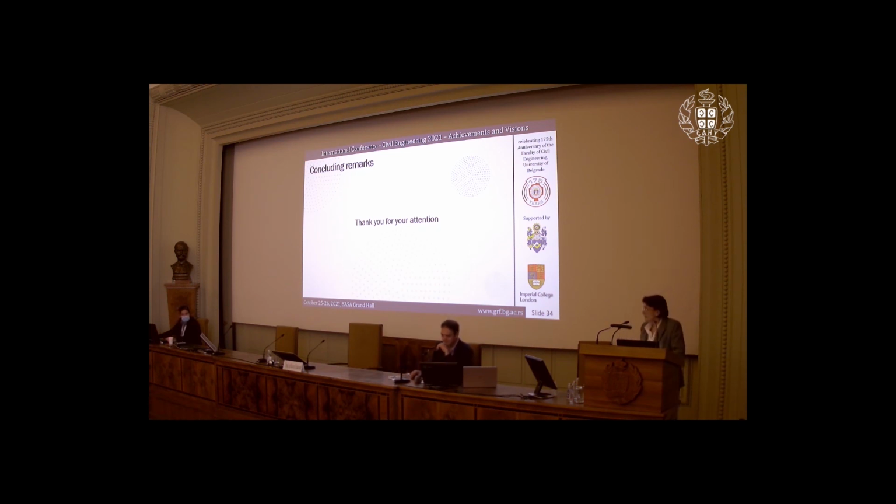I think they have to be integrated with each other. With the field measurements, it's much easier to get the ground profile, like CPT, cone penetration testing, for example, or geophysical monitoring. We can get a continuous ground profile of what is there underneath our feet, and that has a value on its own.